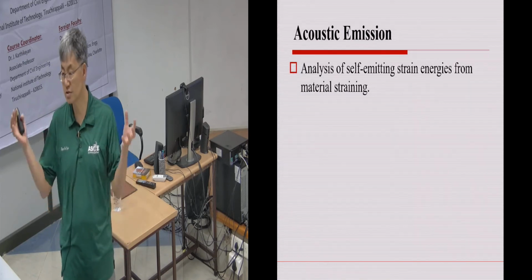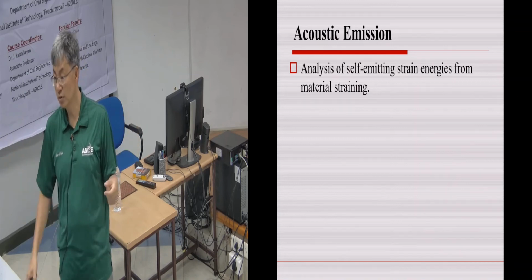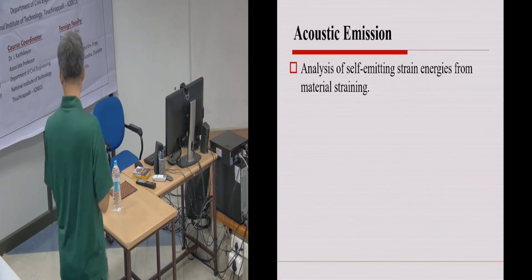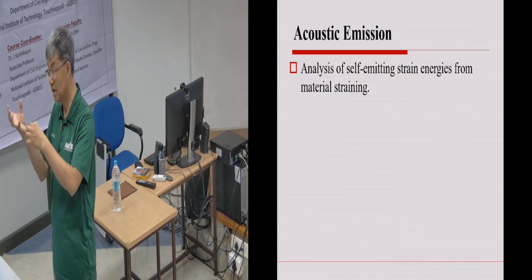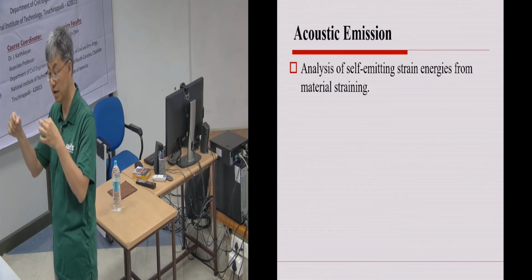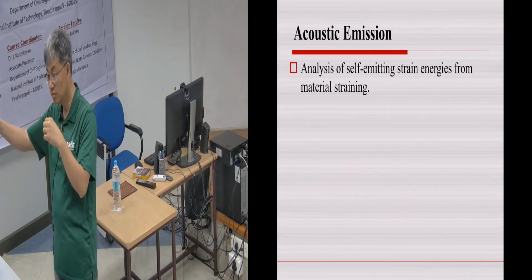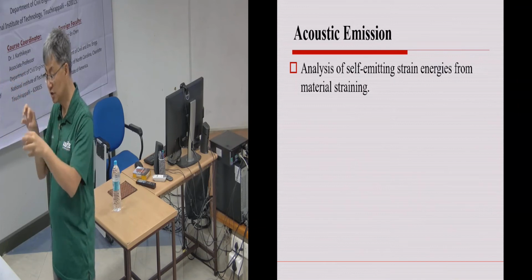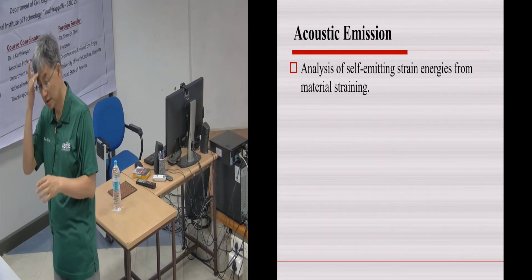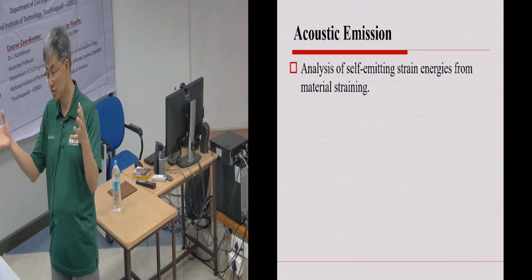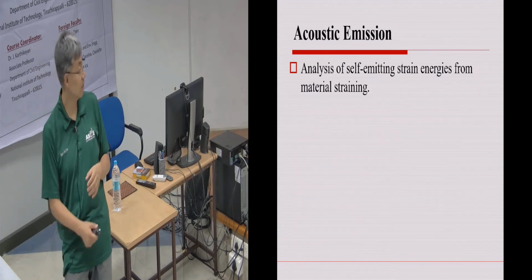Acoustic emission is where the system itself actually creates vibration. It's like when you tear a piece of paper: that sound is actually a strain energy release, deformation energy released from the paper. If it's a small piece of paper, the sound will be higher; a bigger paper, the sound will be lower. By using electronic instruments to listen to this sound, you can tell many things about the structure. But it will only happen if the structure is being damaged, so using this technique becomes critical and tricky.